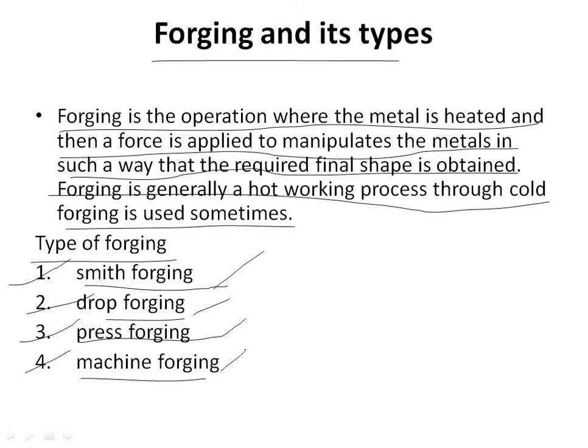Similar to drop forging, it is not possible to get the final shape in a single pass in machine forging. Therefore, the operation is carried out in a number of stages. The die cavities required for the various operations are all arranged vertically on the gripper dies. The stock is moved from one stage to another in a proper sequence till the final forging is ready. A heading tool for every upsetting stage is arranged on the heading side of the upsetting machine.